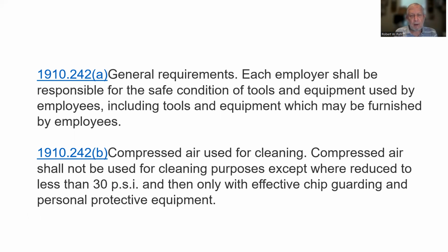And B, compressed air used for cleaning. Compressed air should not be used for cleaning purposes except where reduced to less than 30 psi, that's pounds per square inch, and then only with effective chip guarding and personal protective equipment. That was also mentioned in the previous video for good reason. Those are two things that you are going to need and going to come across. I'm almost positive in your career.